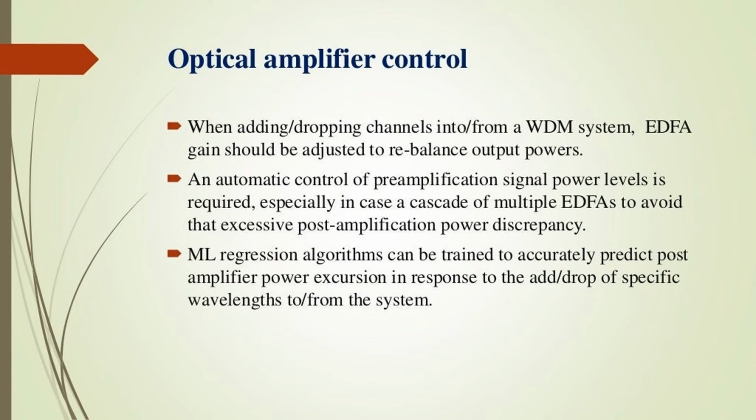Let's see optical amplifier control. When adding or dropping channels into or from a WDM system, EDFA gain should be adjusted to rebalance output powers. An automatic control of pre-amplification signal power levels is required, especially in case of a cascade of multiple EDFAs, to avoid excessive post-amplification power discrepancy.